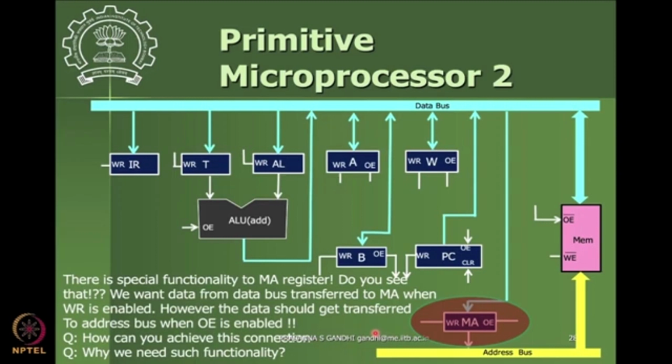We have written a program in some memory locations. When we execute, we need to give the microprocessor a location from where to execute. That location will be the starting point for this memory address register to hold.